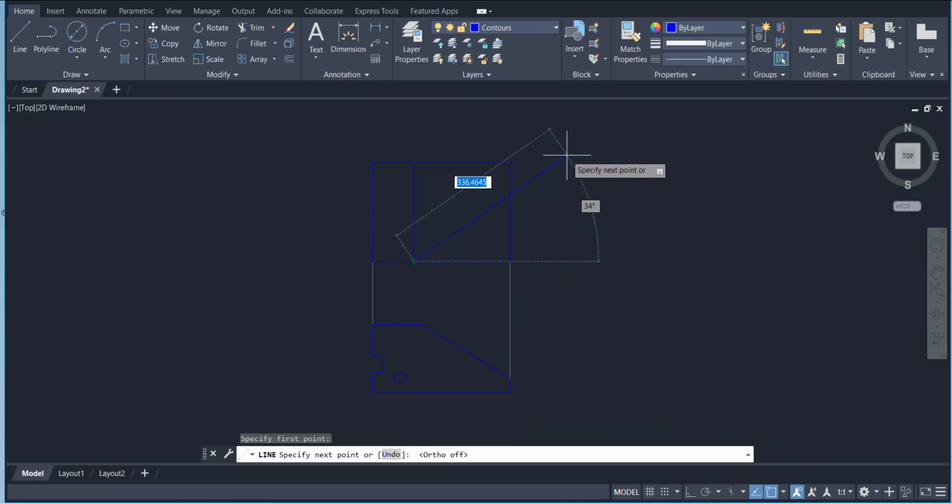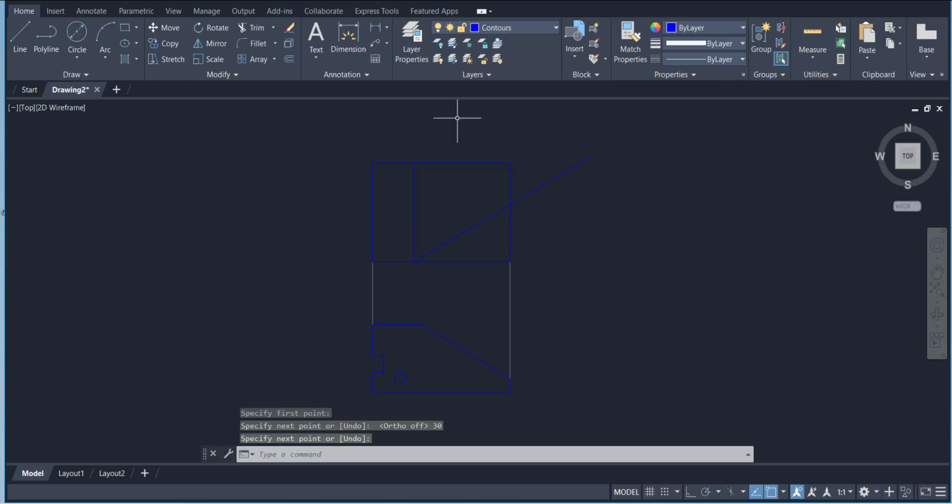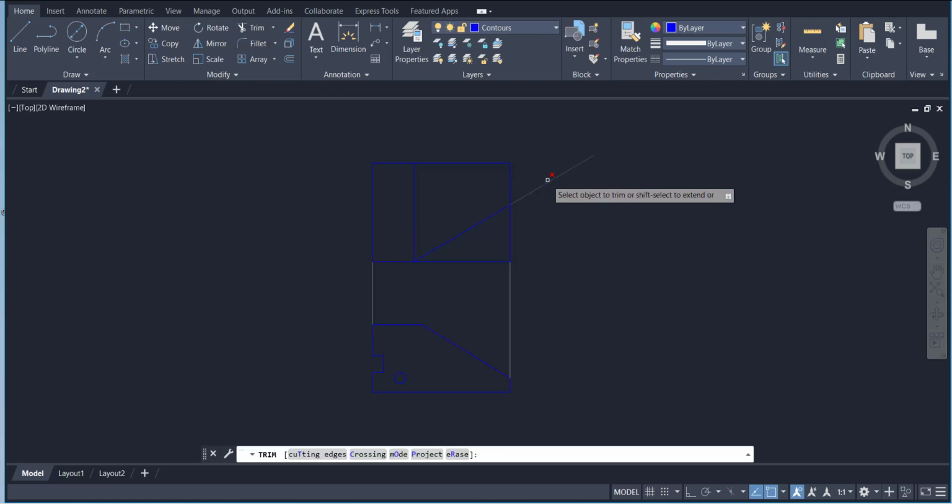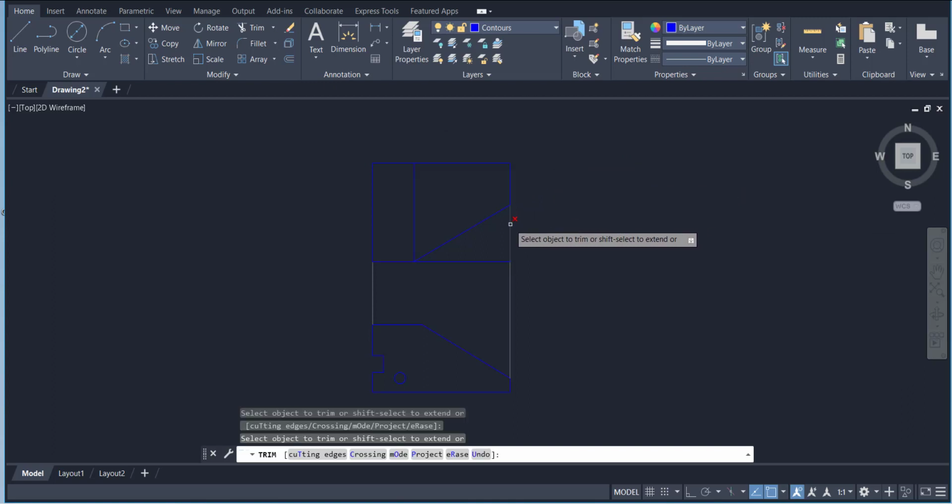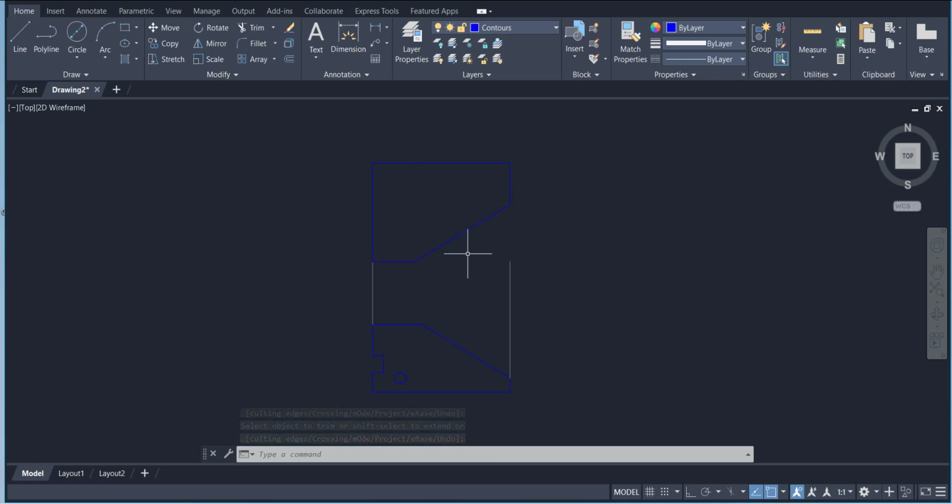So now you can see we can move our circle. So as you know, the angle of this line should be 30. Its length does not matter, only we have to change the angle. So press tab and it's 30 like that. Now you just have to go to trim, and we are going to trim this portion, and this portion, and this portion, and this line we also don't need. Okay, so from this point we just draw this line. All right.